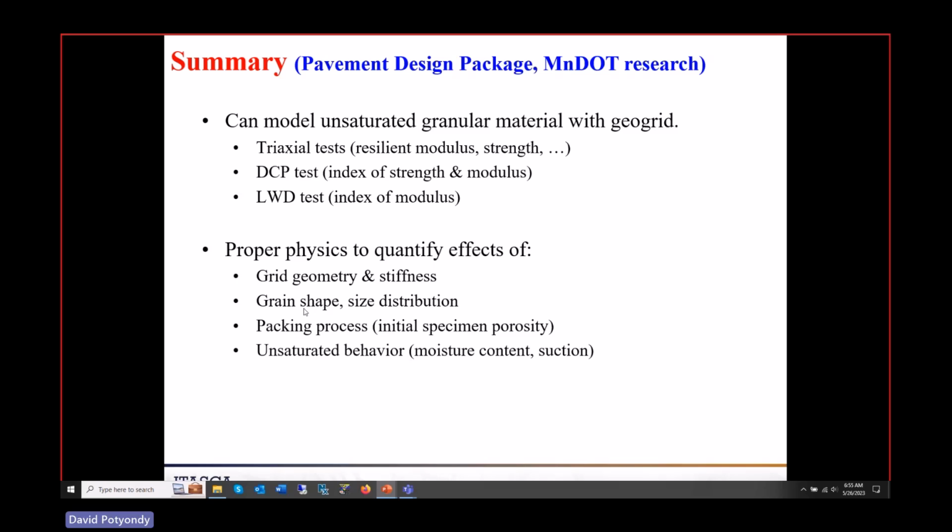For the particles in there, for the ballast, right? We can change the shape of the ballast. I didn't show you this, but instead of creating spherical grains, we could create clumped grains with like 2 or 3 guys that overlap each other. So now they're not just spheres. We could do that. We obviously can control the size distribution. The other thing we specify, because we have that Hertzian model, is the Young's modulus and Poisson ratio of the grain material itself.